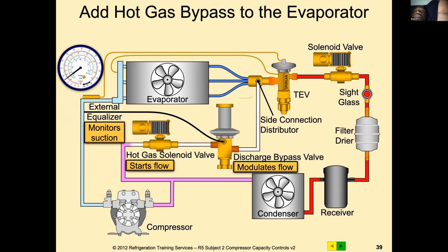I noticed on those fallout ice machines, I had thought that was like a water-cooled condenser, but actually it's a condenser superheating the vapor going into the compressor. It's like a water-cooled condenser, and they're using that to superheat the vapor going into the suction side of the compressor on them Tecumsehs.